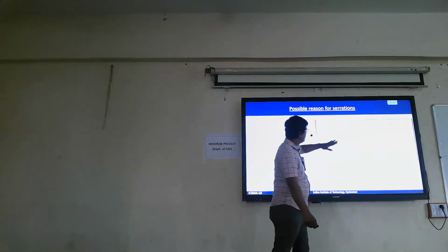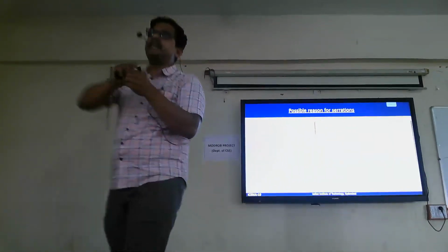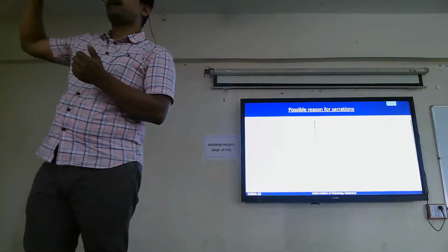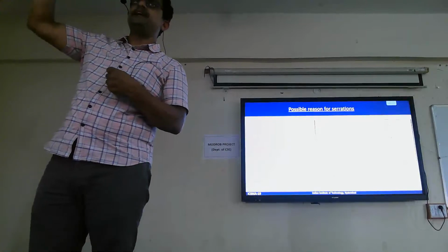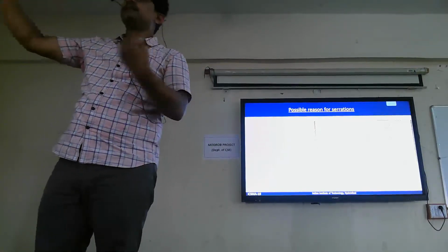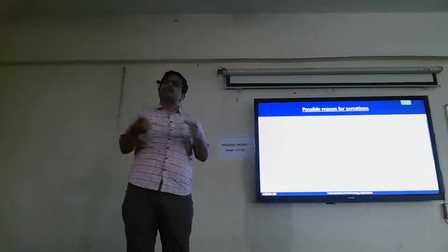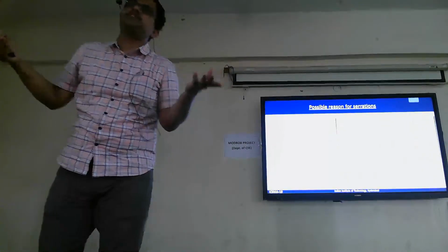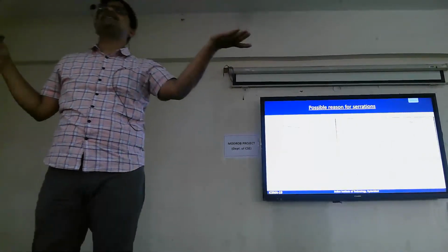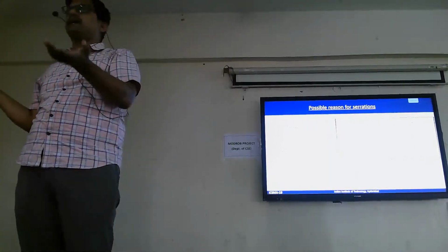And we talk about the strain rate sensitivity. You know what strain rate sensitivity is? It means when you change the strain rate, how it affects your stress. In general, increasing the strain rate increases the stress for deformation. That is called positive strain rate sensitivity. At room temperature, strain rate sensitivity is generally 0.001, 0.002, very low, close to 0. But the moment you go to high temperature, you see strain rate sensitivity of 0.2, 0.3, 0.1, depending on what mechanism operates.